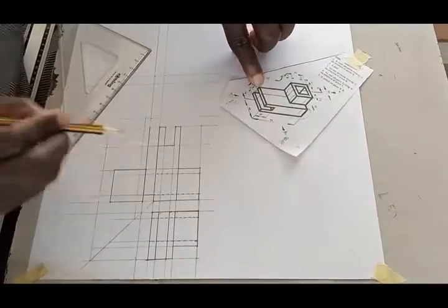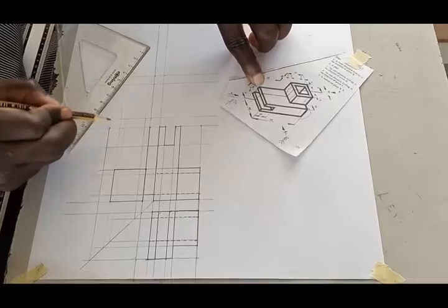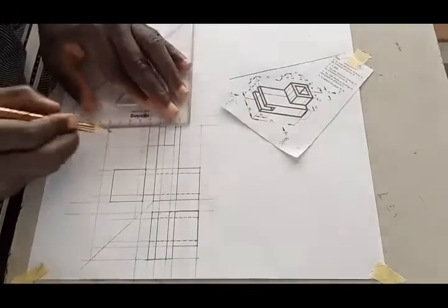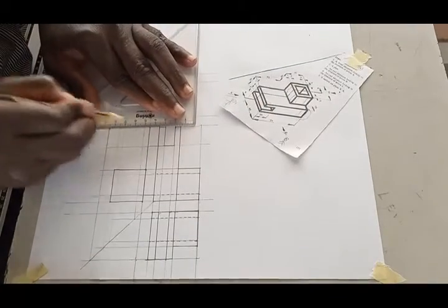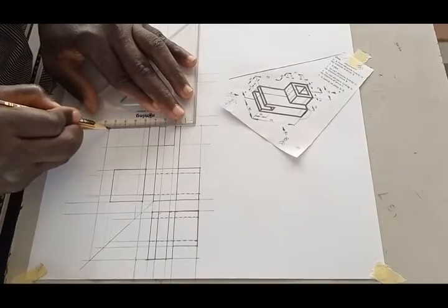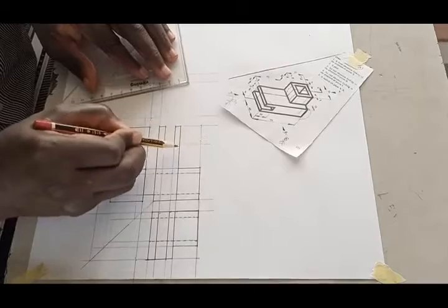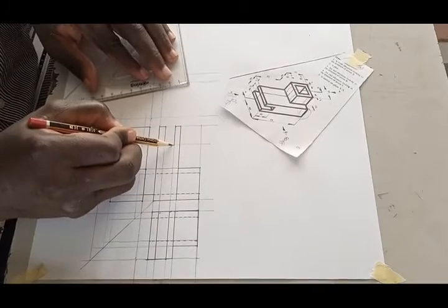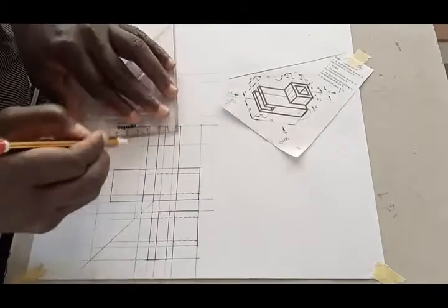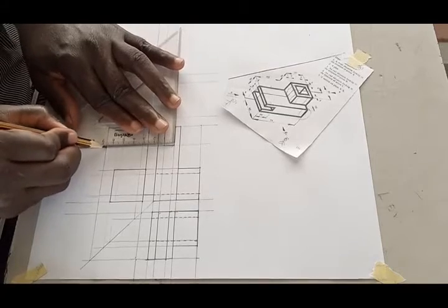Similarly, this end, that is from here to here. This is top, this is the bottom. This is top, this is bottom. So you can see the edge. So you make it thick like that. Now this end, we are viewing from the top. This edge, you cannot see it, but you know that it is there and it's going all through. So you indicate it with hidden lines.